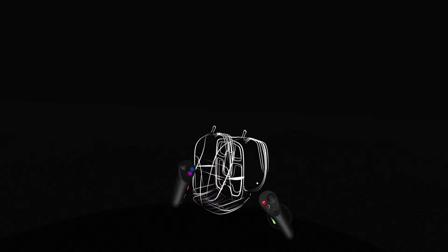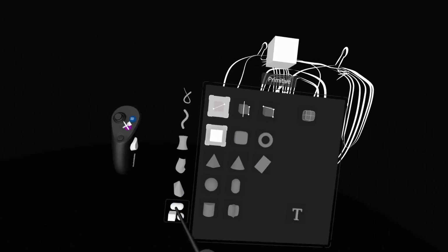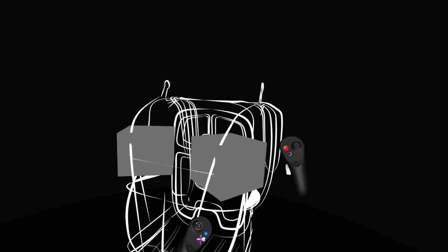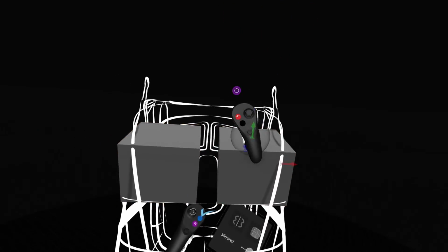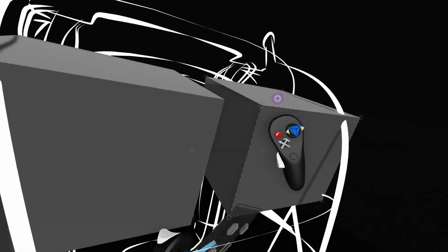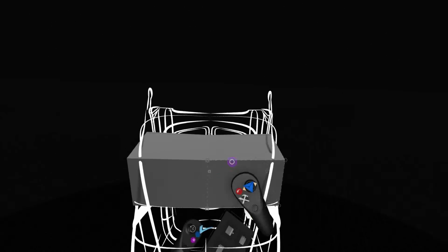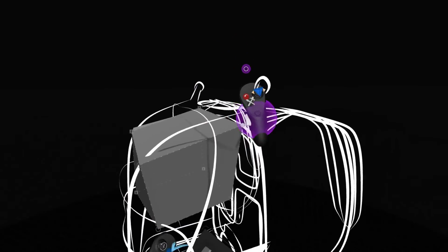Let me just go ahead and delete this bag here. And so what I've found to be really effective is to bring in a cube like this, and obviously you want to give it some shading, and then convert it to sub D, grab this face and delete the face and connect these vertices together. And so now we have a symmetrical sub D surface here.